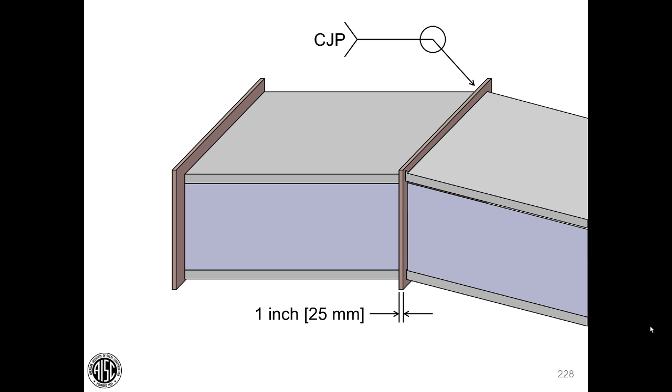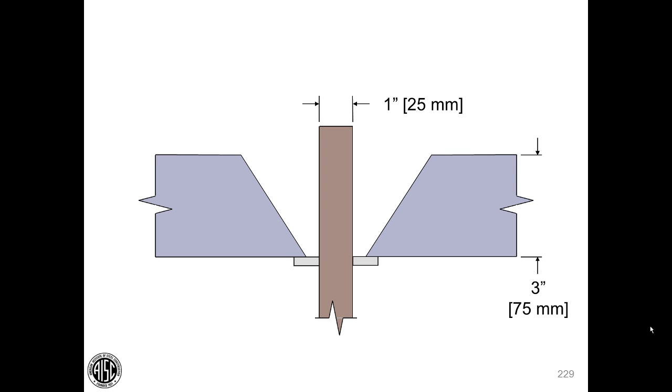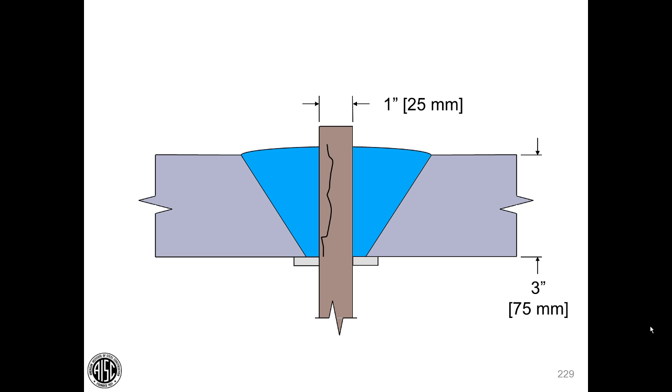In cross-section of the joint, you see the 1 inch plate, the 3 inch plates on the outside that receive the CJP groove weld. And I think some of you will immediately see the problem. What happened with El Paso is they got into lamellar tearing that took place in the brown member. And that was one of the first times that we had a lot of publicity about something that you and I know of called lamellar tearing.